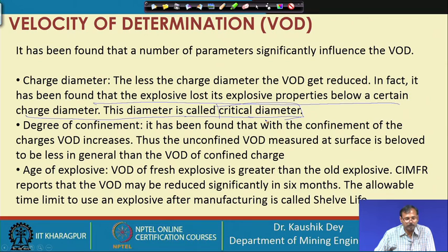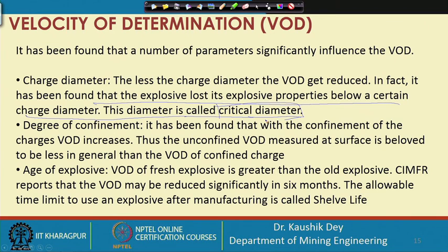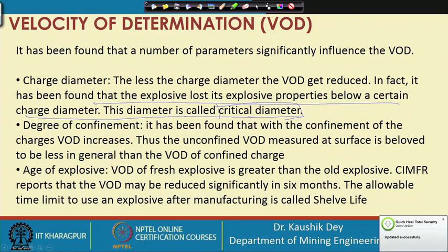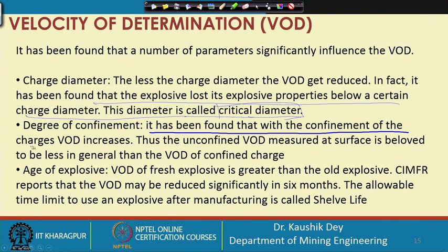Second, it has been found that with the confinement of the explosive, the VOD increases. That means, when the VOD is measured using the Dautriche method on the surface, the VOD obtained is much lower than the VOD obtained in in-the-hole measurement. So, if the VOD is measured in the hole, we can have an increased VOD for the confined condition.